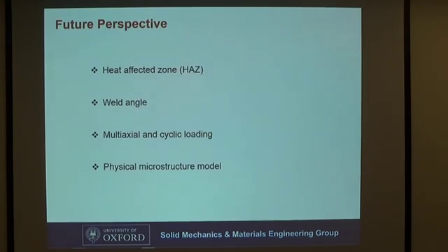And finally, the ongoing work and future perspective. So we haven't considered the heat-affected zones in the material, and later we will consider if you have a different property in the zones surrounding the interface, what will change for the simulation and creep life. And second, you cannot guarantee the weld angle is perpendicular to the loading direction. So there may be some different angles. In that case, the tangential traction will take effect. So we need to consider the interaction between the two tractions.